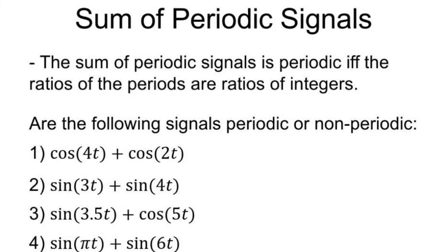We are using the same principle. First finding the period of the individual signal by using T is equal to 2 pi by omega, and find the ratio T1/T2. If it is a rational number, then we can find the period by taking the LCM of T1